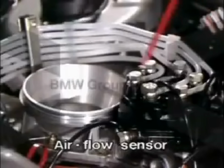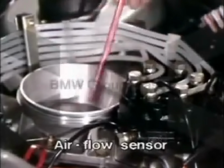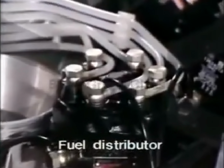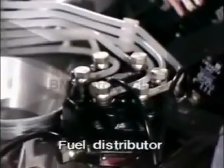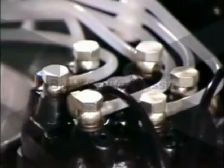At the mixture control unit, we differentiate between the airflow sensor and the fuel distributor. The fuel distributor has the task of providing a correctly measured amount of fuel relative to the inducted volume of air and of distributing this amongst the individual cylinders.